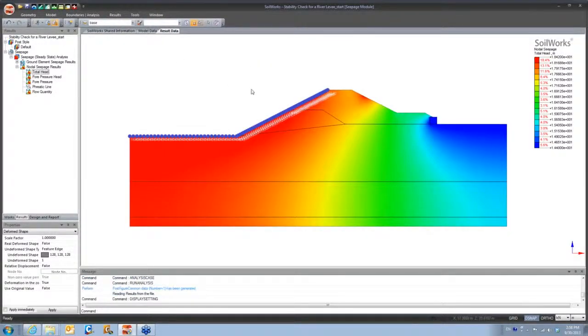Okay. So yeah, since the water pressure is high on the left side, all of that's in red, and then it goes sort of off into blue because there's no water pressure on the right side. So typically with FEA software, all the critical or higher results are in red, and the lower ones are in blue. And then just using the contour graph, you can judge at a glance what your values are for your head, your pore water pressure head, etc.